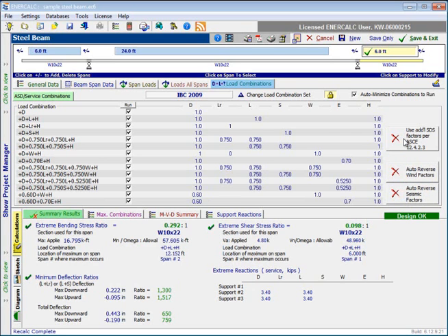And then there's a button up here called Use Additional SDS Factors per ASCE, where we can enter some non-zero value for SDS. And when we do that, the program will automatically go in, and when we see these load combinations generated in other locations, they won't display this factor here, but we'll see it when we get to results.